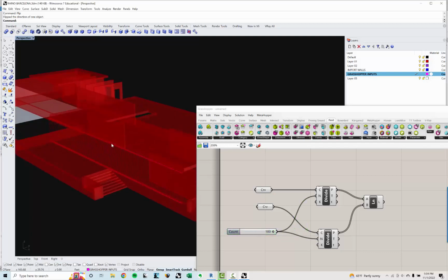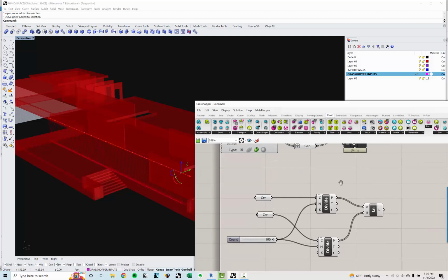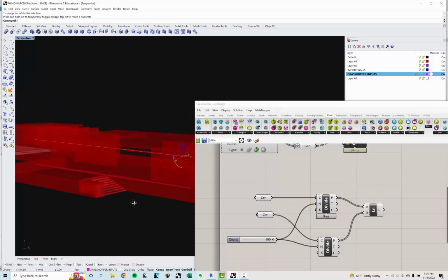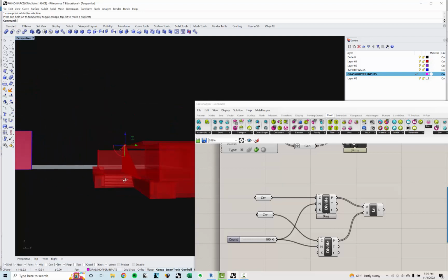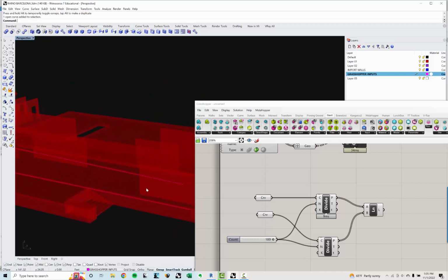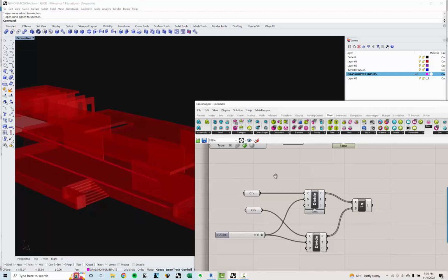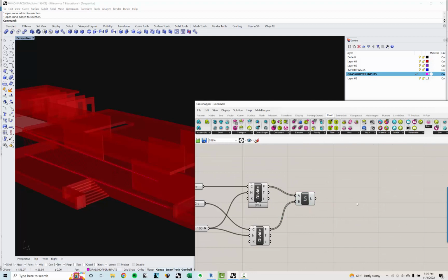Okay. So now, my recording just accidentally stopped there, so I'm going to try to pick back up where I left off. I was in the middle of working on this Grasshopper definition, so I could pull this out and do more of a curved surface or a ruled surface or something like that with a little bit more complexity to it. Again, I'll let you guys go wild with this, but this is something that would be pretty hard to model in Revit natively. And so if I was just going to take this and maybe do an extrusion or a sweep along this for a screen wall.